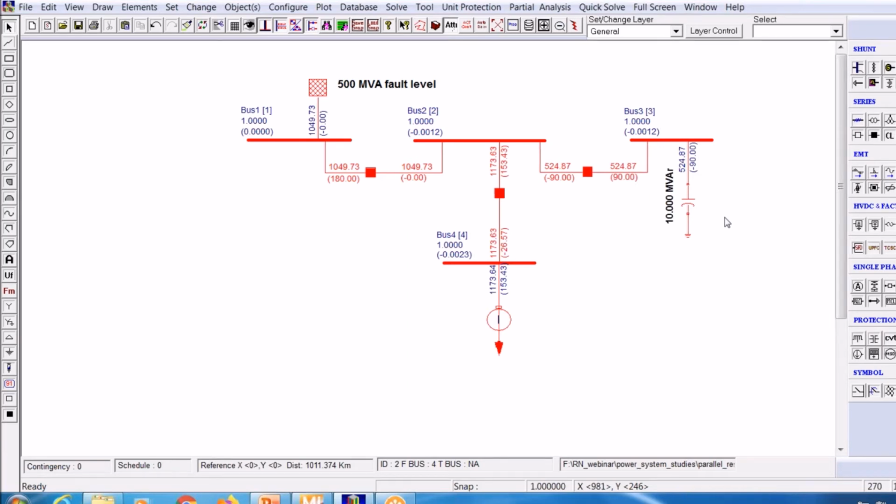What it means is, in this system, you are injecting a current here. It has two parts, a parallel path. One is the inductive part here, and this is a capacitor here. There is an injected current with a parallel shunt inductor and shunt capacitor. But these two, the inductor and capacitor, at the seventh harmonic are resonating. It's a parallel resonance condition. You are injecting a seventh harmonic current there. What will happen? It is offering a very high impedance for the flow of the current, which implies the seventh